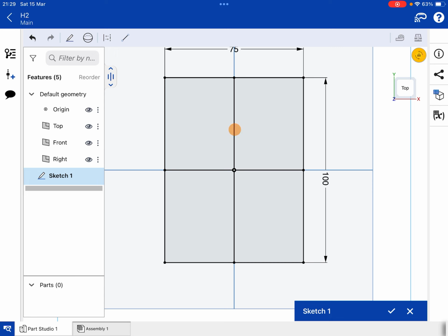The way we do that is we press on the line we want to work on, so in this case that vertical line, and then we go over here where it's got that little icon there. And we can see by pressing that, I've turned my solid vertical line into a dotted vertical line. So now it's a construction line, right? And then I'll do the same thing on my horizontal line, press that, and now it's dotted as well. So now we've got our 2 reflection lines or mirror lines, and they're going to be construction lines, so they won't appear in our final design.